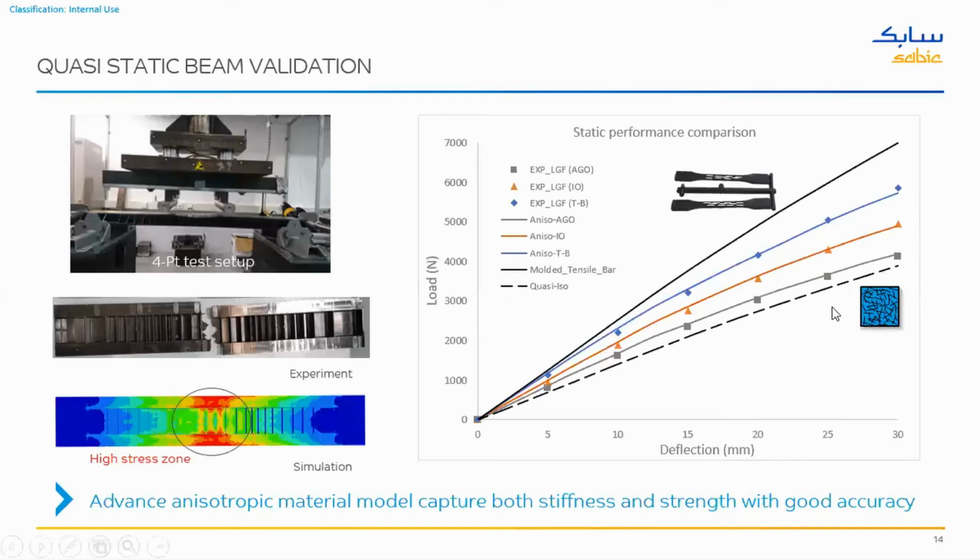On the other hand, if he uses the advanced modeling technique with the anisotropy, taking the process-based fiber orientation into his design, then he could achieve the maximum advantage from that fiber orientation and be able to reduce more weight in the part.